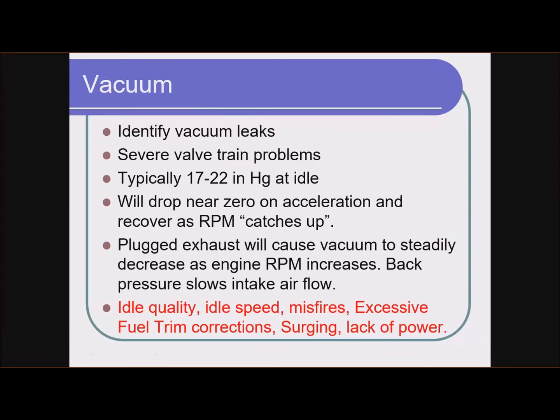So why would we be doing a vacuum test on a car? Well, again, if you look at the bottom, the red, right? Idle quality. Now maybe we have a rough idle. Idle speed.